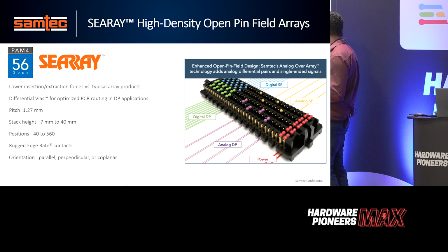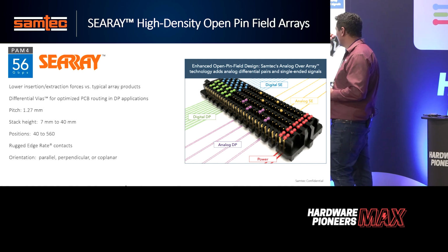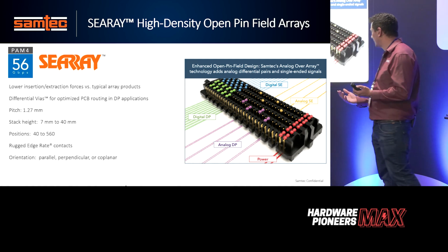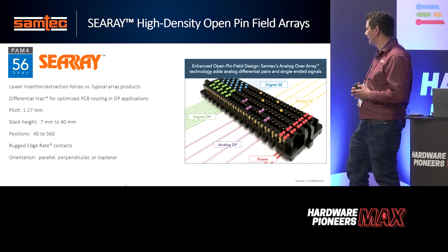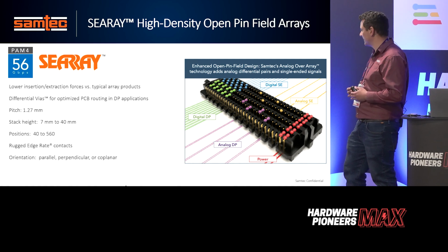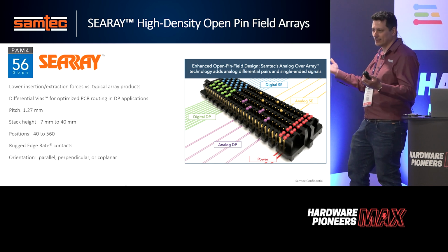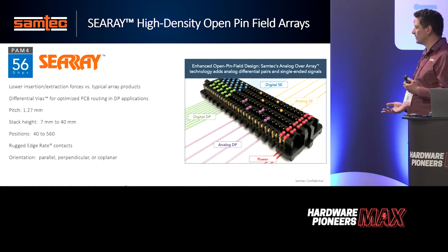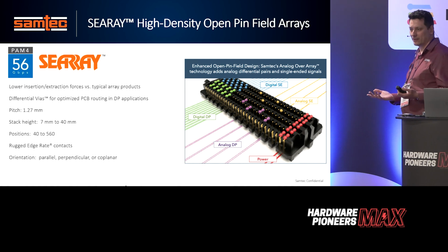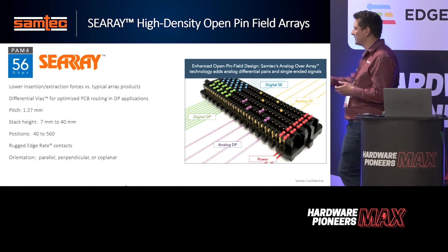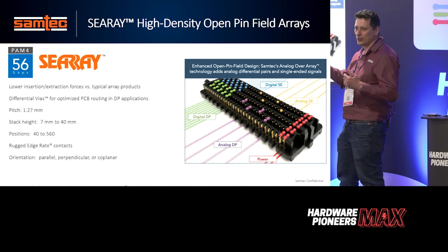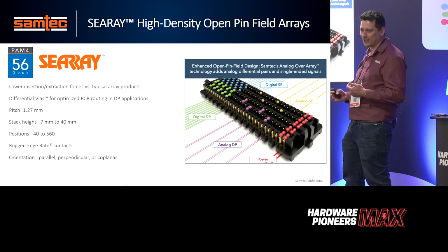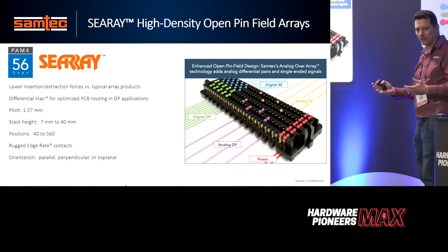So what we are doing recently, especially since the advent of RF SoCs, we had some silicon partners coming to us and saying, okay, I have this RF SoC that now offers the functionality of getting RF signals directly into the chipset. Can I use your connectors for that? So if we look at the S parameters that we did back in the day, we can see that return loss and insertion loss, it's really good up to certain frequencies. It really depends on the stacking heights. When we mention here 56 gigabits performance, it doesn't mean that you can do 56 gigabits on every single stacking height from 7 millimeter to 18.5, because the S parameters will change quite a lot from one height to the other.